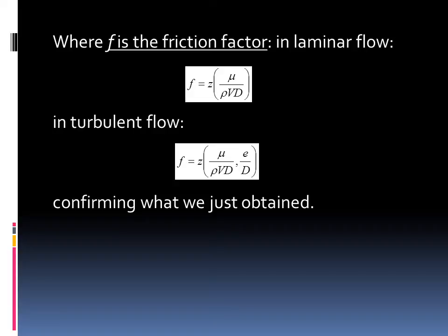Also, though experimental data are necessary to determine the relationship, the Pi theorem can help us by providing the best way to do it. Otherwise, we would have to study the influence of every single parameter on the pressure loss, all 6 of them, independently, represent the data, and make sense of it. However, using dimensional analysis, we would only have to study the influence of 3 dimensionless parameters, making the process much simpler.